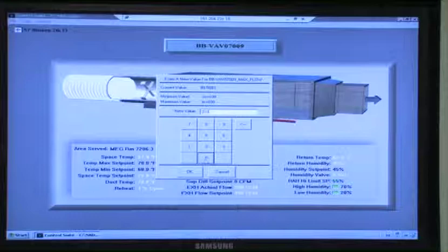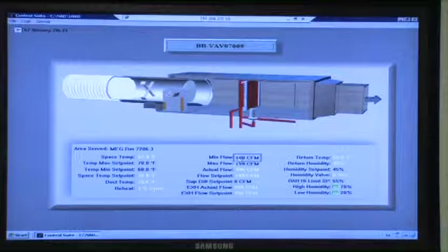So it is a VAV, huh? It's going to be interesting. And min flow is 100? Yes. Actual flow, we'll see, flow set point 100. What about the differential? I believe it's a neutral room. If it's a neutral room, as long as I leave that at this, it'll track whatever the supply currently is. It's going to track the actual flow, maintain the flow relationship. And these should be matching.